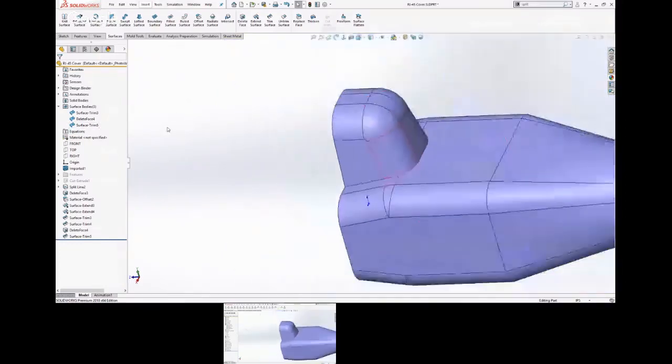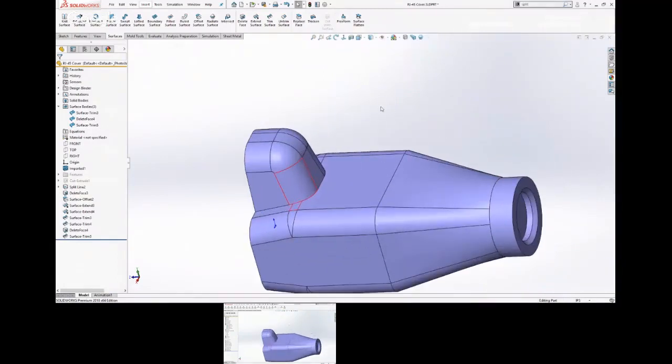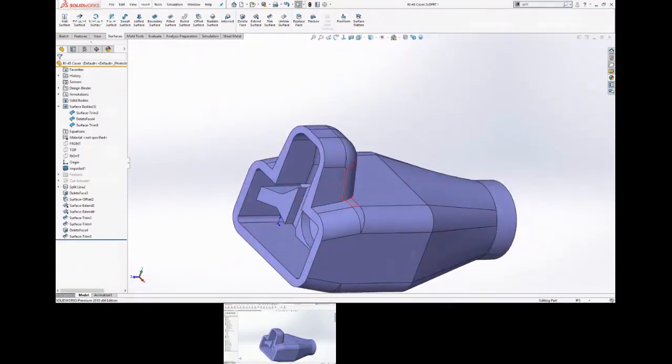So the last final thing is that back in the day, to create a mold for this, to use a cavity feature, you couldn't use a surface body. You need to have a solid body. For a surface body to become a solid, it has to be watertight. There can't be any gaps in there.